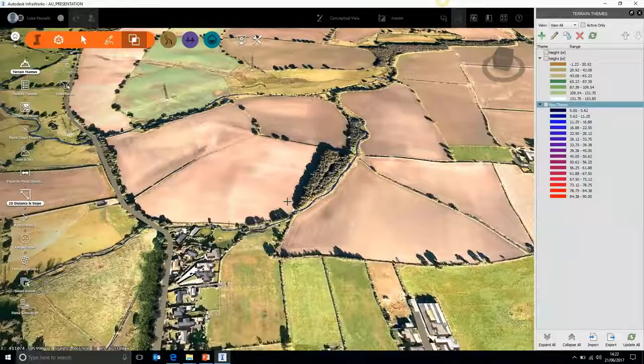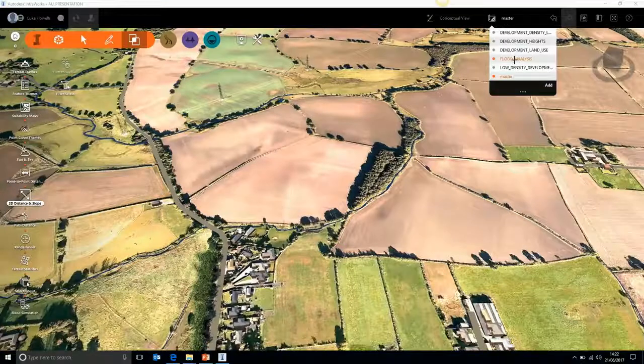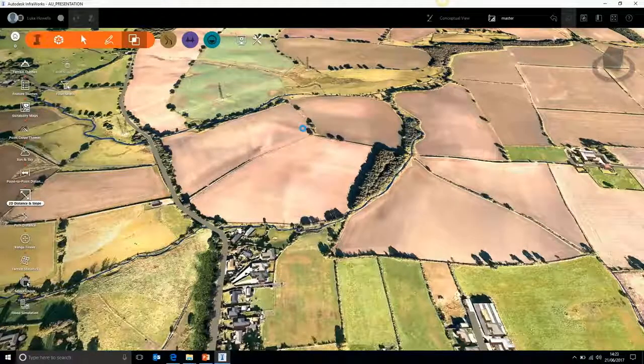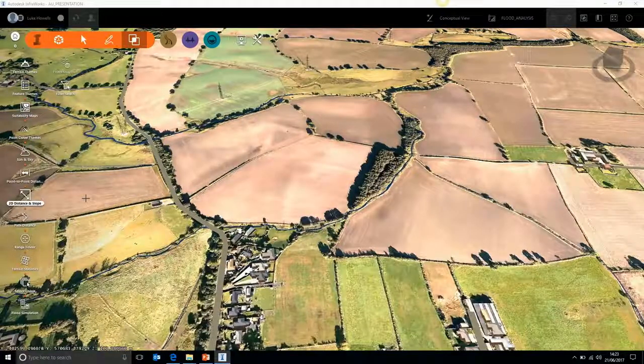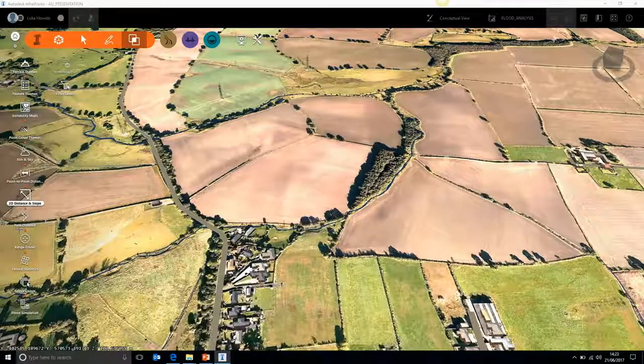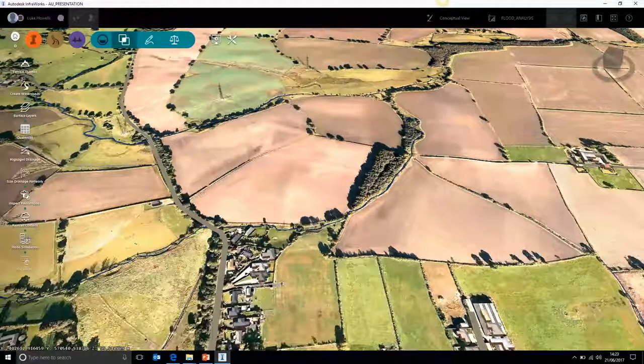Okay. So, another analysis we can do over the top of this is actually using a third-party application that's added into the software itself. So I'm just going to flick to a flooding analysis. The third-party software I'm currently using to run the analysis is a product called Hydronia. It runs basically as a cloud-based service. So you can go in and select the area you actually want to use. You can select the input for your water courses, select where it's going to discharge to, and then you can run your analysis itself. So if I just step into there, we will run an analysis, our flood simulation.